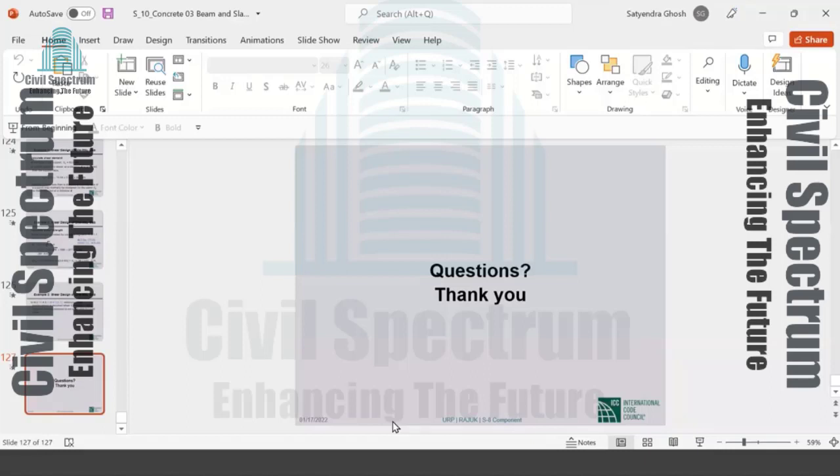But if you have beam supported slabs, then the load applied on the slab is transmitted to the supports by bending in both directions, the short direction and the long direction. Short direction bending transmits more of the load than the long direction bending. The short direction is stiff, the long direction is flexible. The stiffer direction transfers more load.